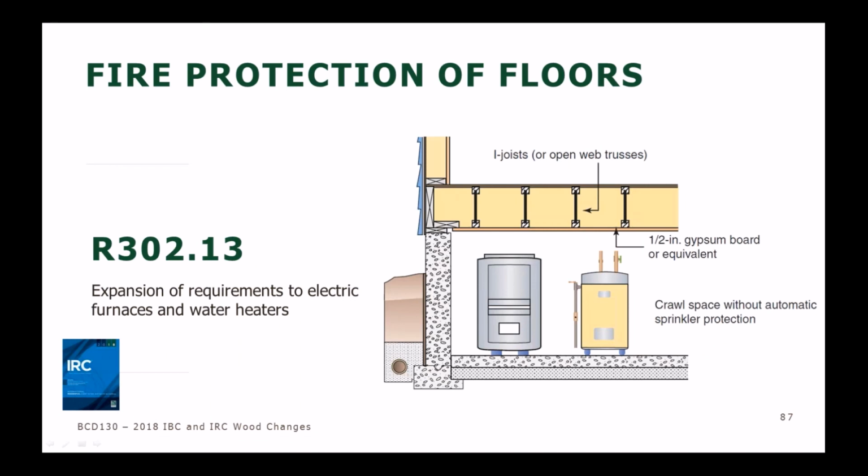It's the IRC table 301.6 that has the live load requirements, and it continues to have 40 PSF for decks in that table. So the 1.5 times requirement only applies to decks that are covered by the IBC. That's where that specific requirement comes into play, not for decks covered by the IRC.